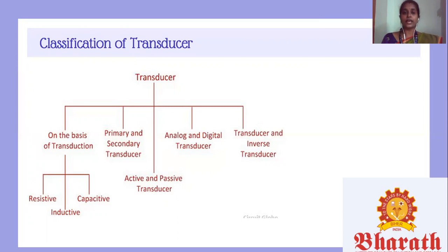The transducer can also be classified by its output signals. The output signal of the transducer may be continuous or discrete. The next kind of classification is analog and digital transducers. The analog transducer changes the input quantity into a continuous function. The strain gauge, LVDT, thermocouple, and thermistor are some examples of analog transducers. The transducer which converts the input quantity into a digital signal is called a digital transducer. The digital signals work either on high or low power.